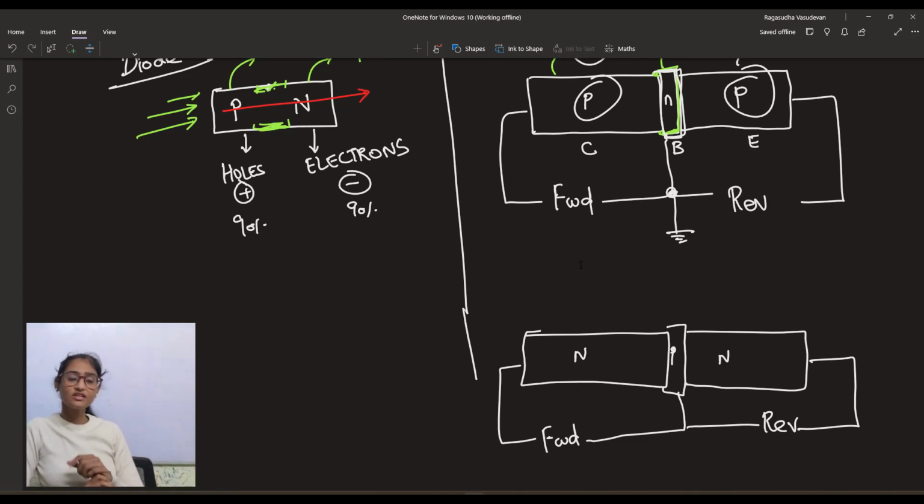What if I am forward biasing both these terminals? This is called the saturation region of operation, and in this region the transistor will be magically transformed into a wire, where conduction is so maximum that it is equivalent to replacing that transistor with a wire. Usually we use a transistor in the active region, where it operates according to the curve that is present in the data sheet. So it is safer to operate the transistor in the active region. When you are using a transistor in saturation mode, it means that it conducts to the maximum possible extent, which is the same as the input current, and the transistor is not generally used in saturation mode. Actually, you will always use it in the active region.